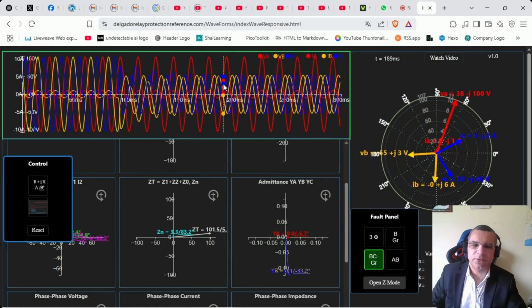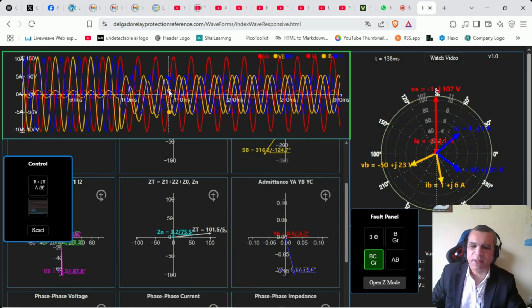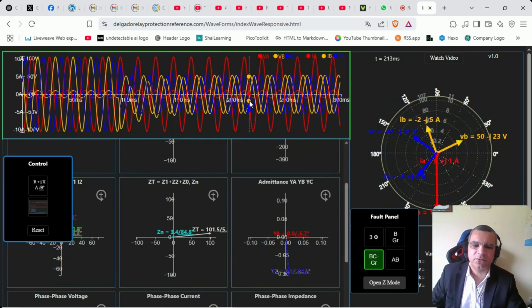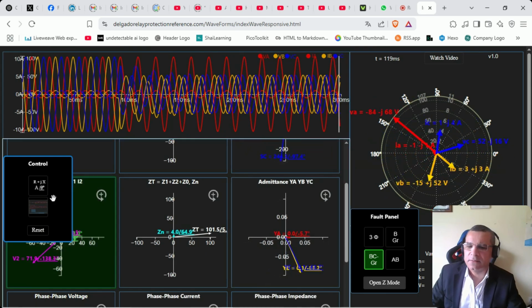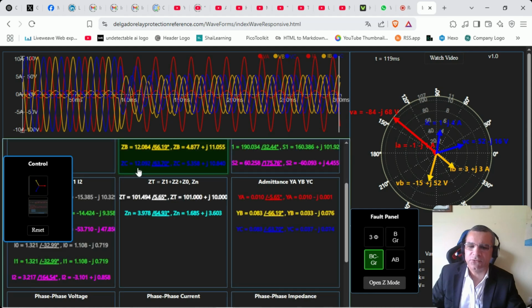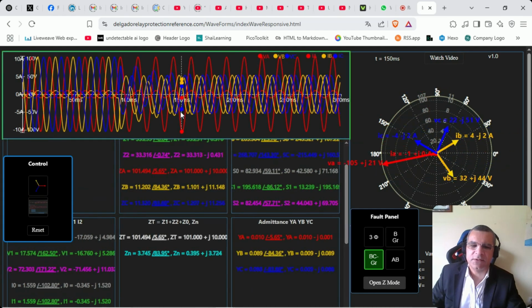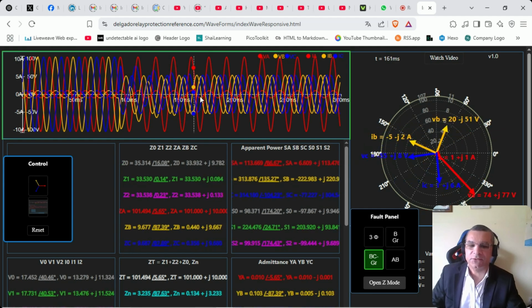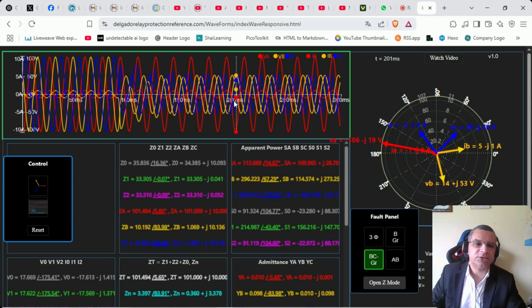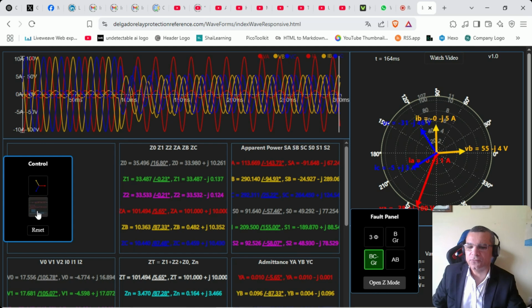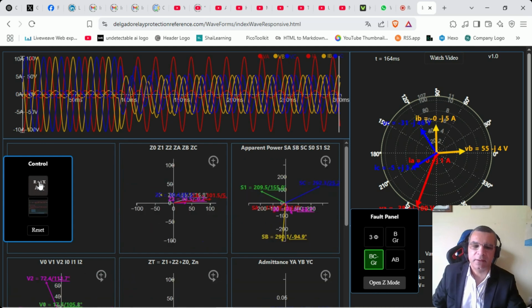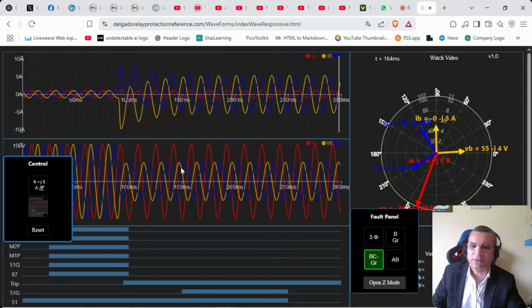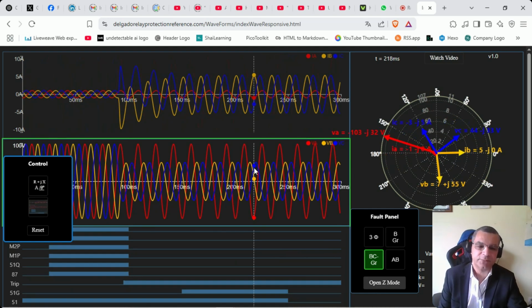You'd be able to see how all of these are impacted by the fault. You are able as well to get the instantaneous values as impedance on the polar or Cartesian values, right? So this is a nice way for flexible interpretation of each of these impedance values.